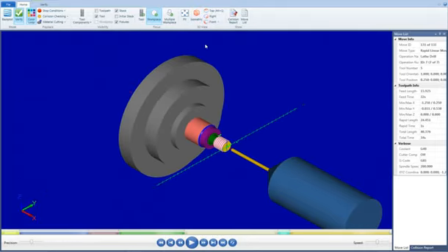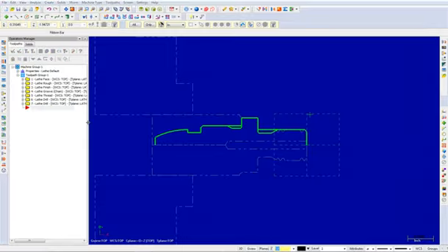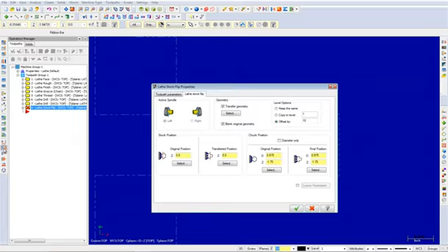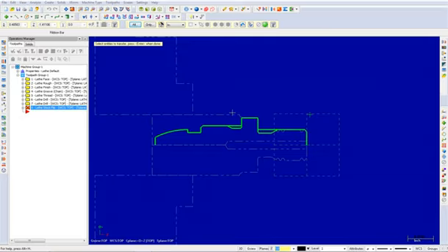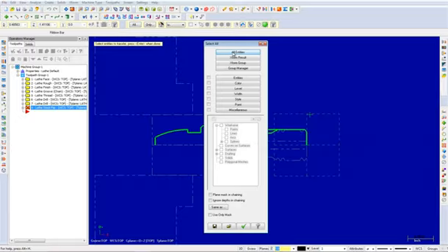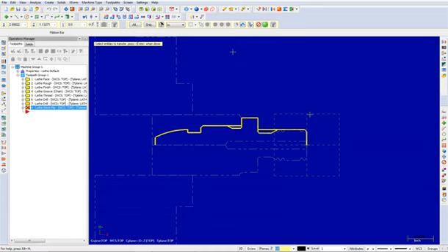Now select the Exit button. Once you have verified your toolpaths are correct, select the stock flip icon. When the dialog box appears, we need to choose the Select button to pick the geometry we want to flip. From here, select the All button, All Entities, and hit Enter to end the selection process.